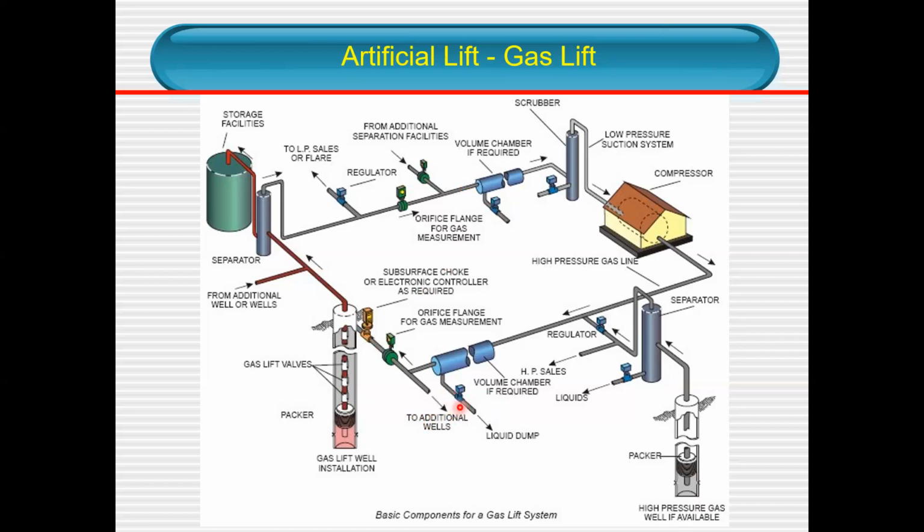This is where we have another responsibility, to find wells where we can inject the gas back into the reservoir. So when the production comes out, the gas comes out, we want to treat the gas, whether we want to treat it back into the same well or inject it into another well, high pressure gas. If this is another well, it gives you the gas to inject into this gas lift well.